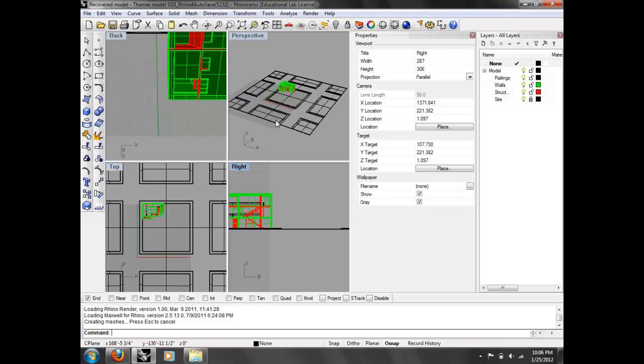Okay, what it doesn't do well: it doesn't have parametrics by default. You need a plugin like Grasshopper to do parametric design. It is a destructive modeler, which is another thing. So when you use two objects to make a new object, those two objects disappear. So it doesn't save a history of those things in the way that other programs do. That could be valuable. It also doesn't do anything with animation, or it doesn't do it very well. It doesn't do rendering and materials very well out of the box. So there are reasons why you'd use other pieces of software. But for what we're going to be using Rhinoceros for today, and what we use it for as architects, it's very good. I'm going to go ahead and close these.